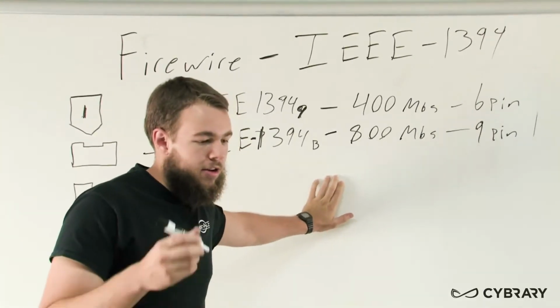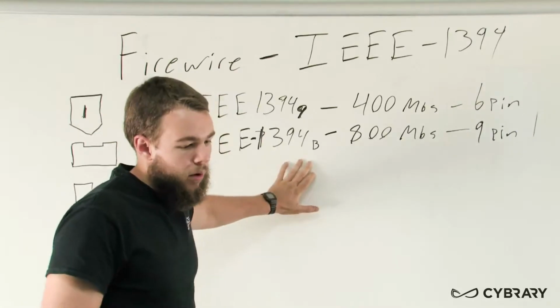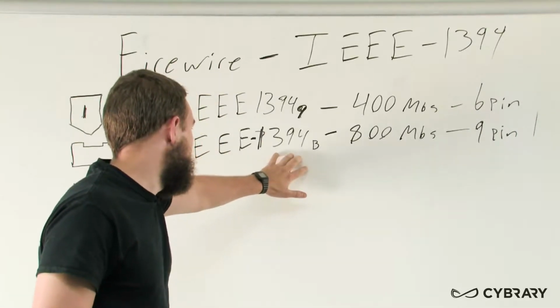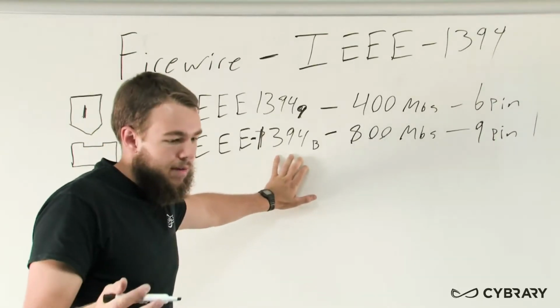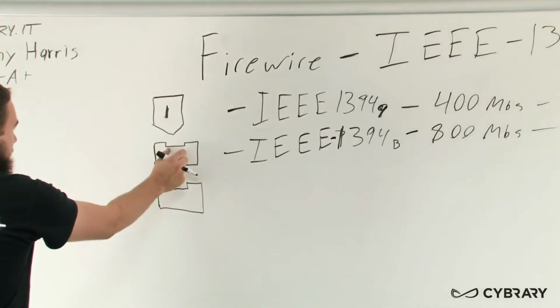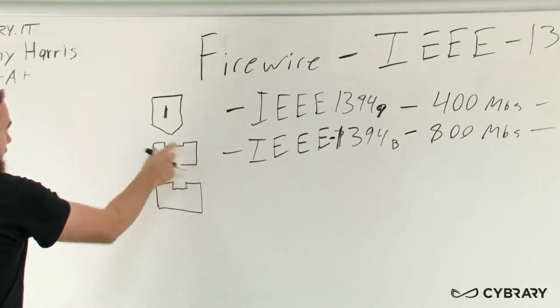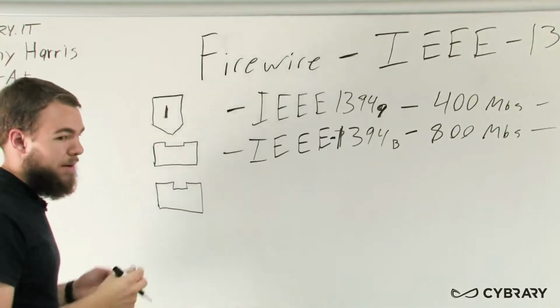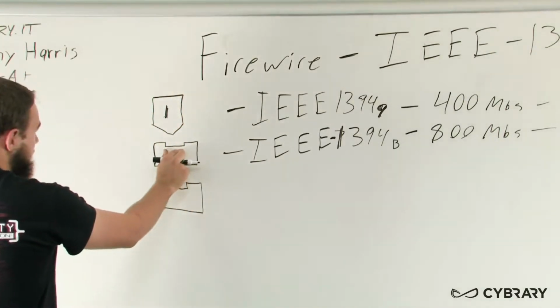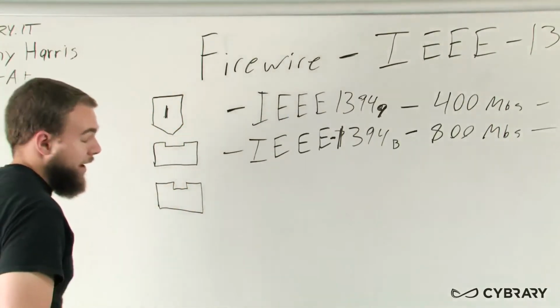It's a 9-pin connector. And for our beta port, when we're just communicating with 1394B to another 1394B, we just use a single port here with the wider keying notch at the top, and it communicates across that Firewire cable. Both ends are this same 1394B connector.